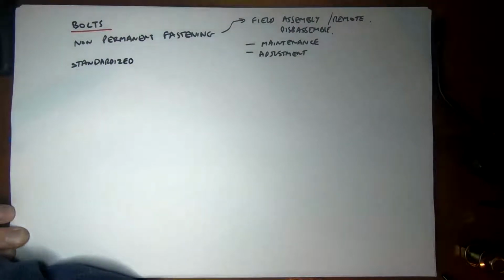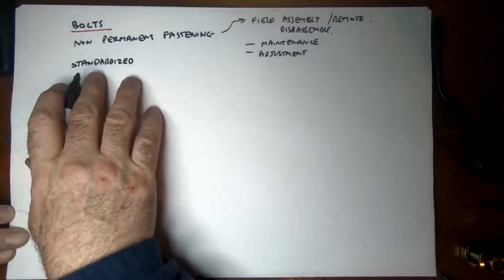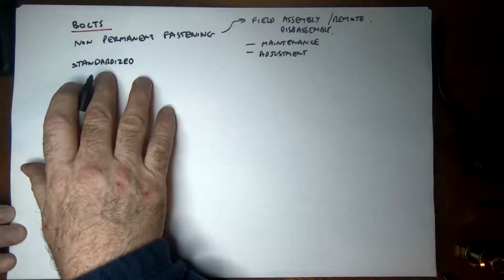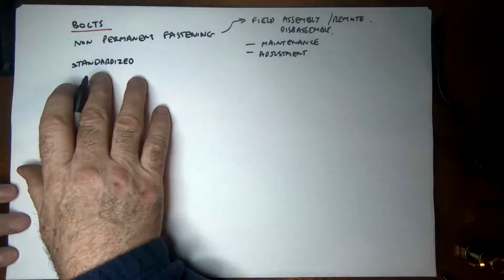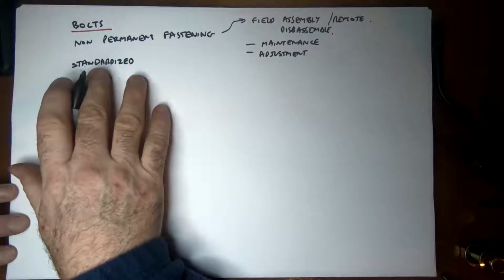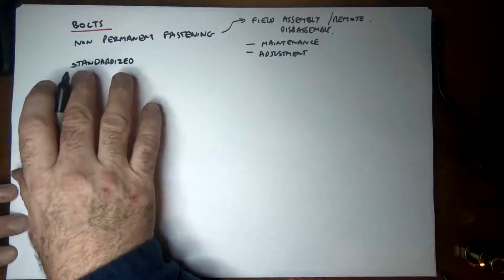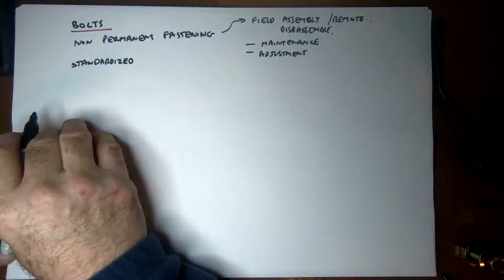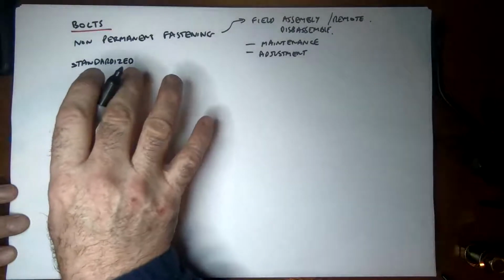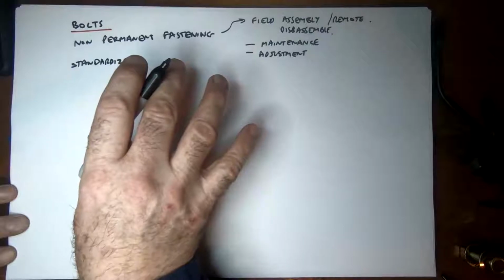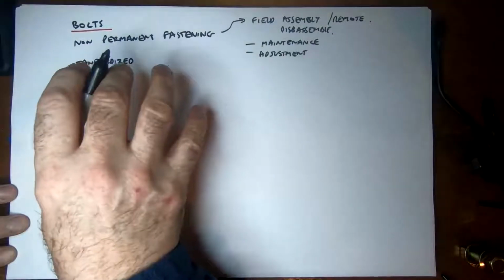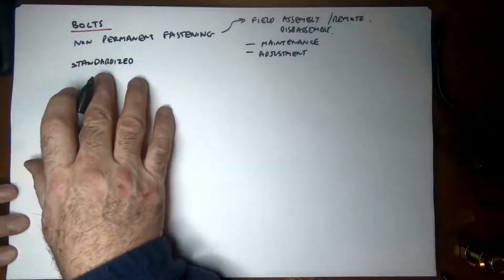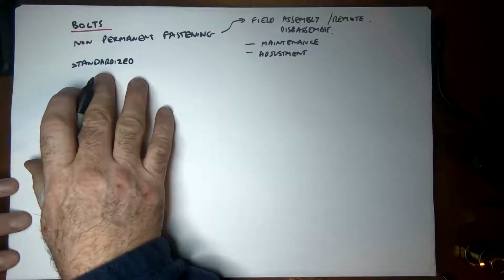I worked for a company called Lucas Aerospace, which made the starter motors for aircraft engines, and we were a metric company, so all the stuff that we made was metric, but it was going on an American aircraft, so we had to make the external casings with American standard threads, which was great as long as nobody ever took one part, the inside apart, and had those bolts mixed up with the external parts. Then you'd have a complete mess. So we are better than we used to be, but we're still not universally standardized.